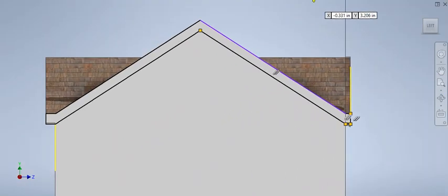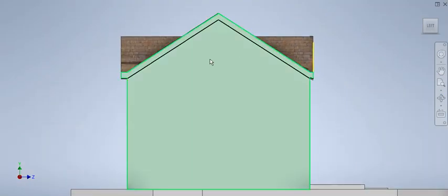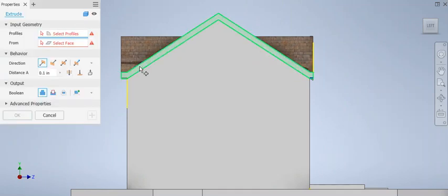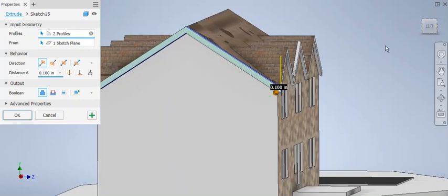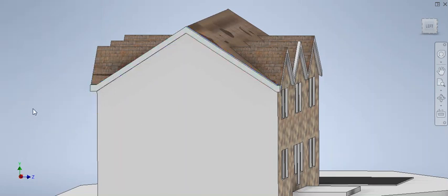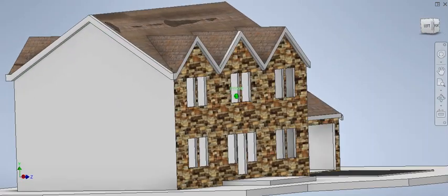Okay, and now I'm going to finish the sketch and attempt to extrude 0.1. Extrude command, select the area, change to 0.1, and look at this, change the direction so that we can see if it is correct or not. Okay. The one trim is generated, created.